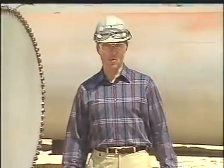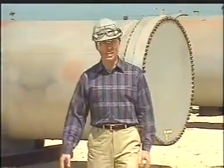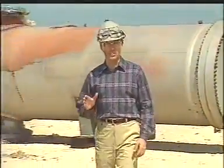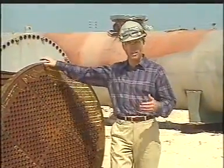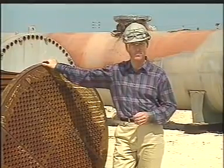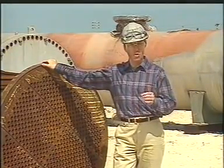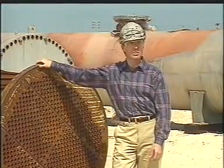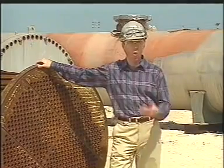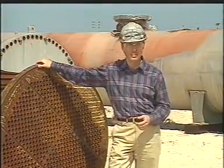Leaks are another important maintenance concern. Whenever exchangers are down for cleaning, they're almost always tested for leaks. But before dismantling the exchanger, there are some preliminary tests you can perform. One simple way to test for leakage is to take a sample of the lower pressure fluid and check it for contamination. If the fluids are very different in appearance, like oil and water, just looking at the sample should tell you if there's a leak.